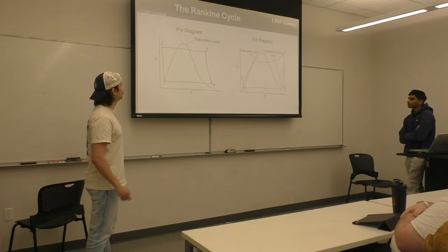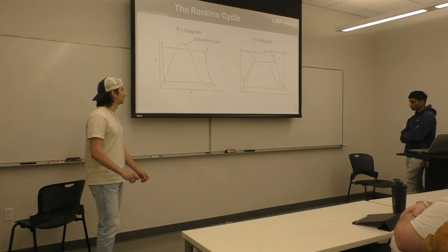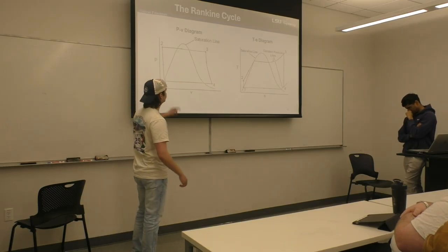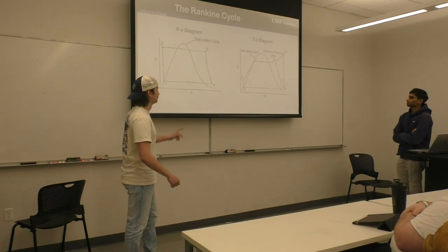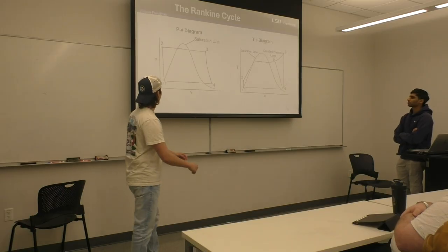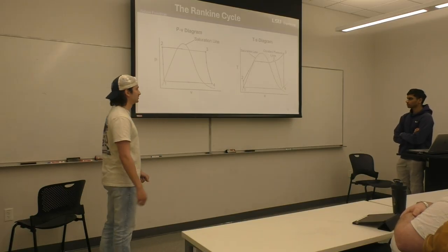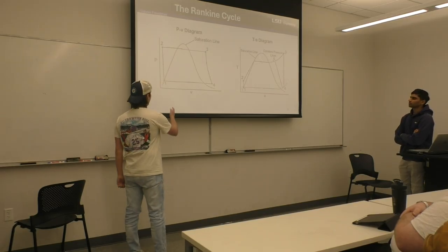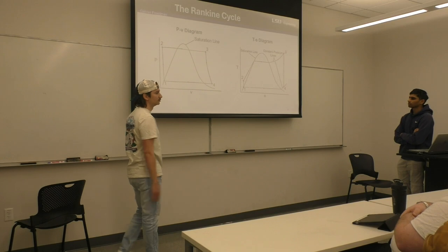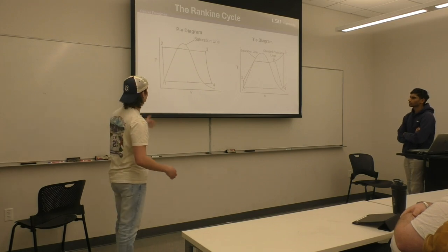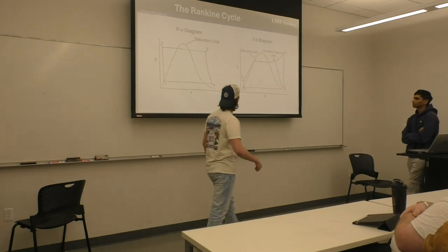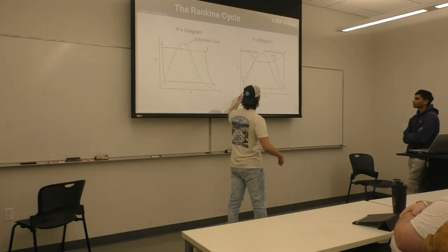So basically 2 diagrams that help guide this experiment are the PV diagram, pressure and volume, and the TS diagram, temperature and entropy. These are basically guidelines for the ideal states. So you look from 1 to 2 over here, it maintains constant volume, or ideally it will. And then 2 to 3, constant pressure. Then you move over here and you see 1 to 2, constant entropy.